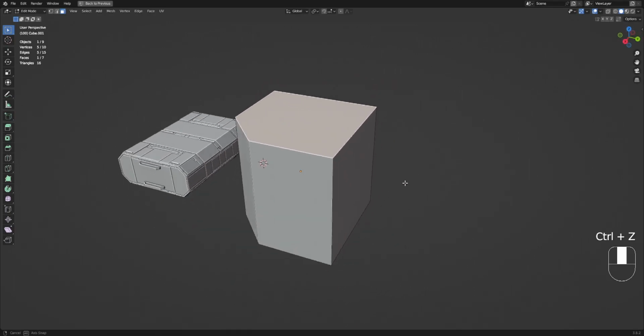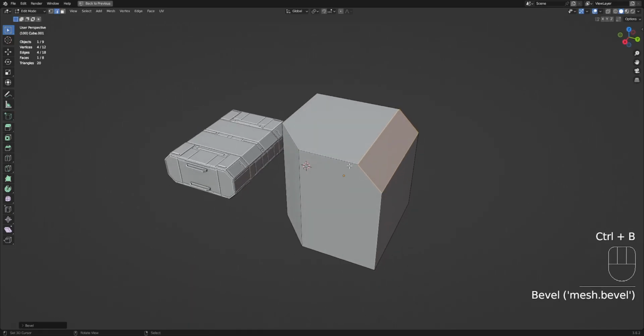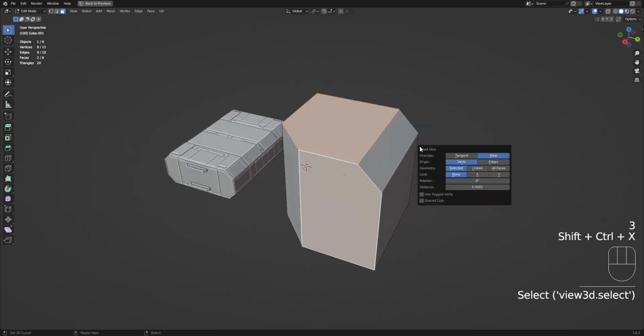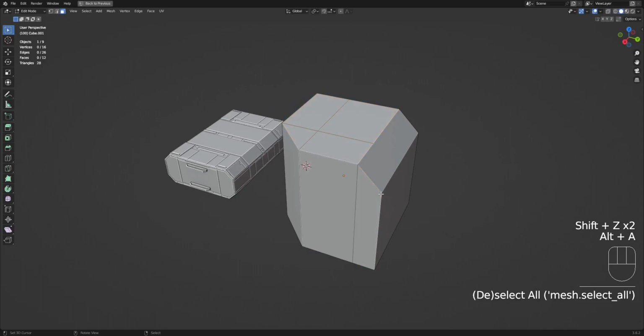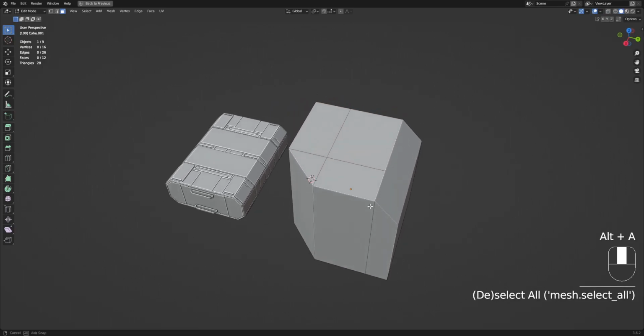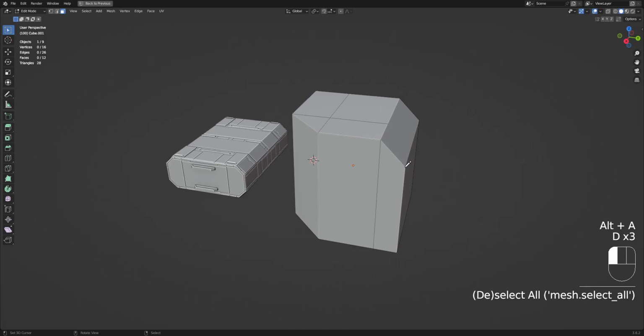Okay, and also the selection must be in the same plane. If you select this and this with tangent, you can see that it's not working for this side here. So the edge that was probably used for cutting was from this face. And you can see that it's not working right here. It's supposed to cut like that.